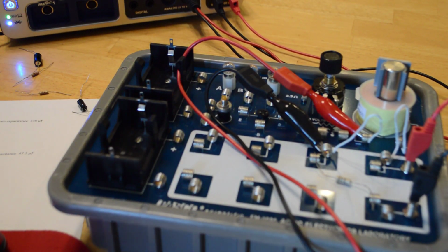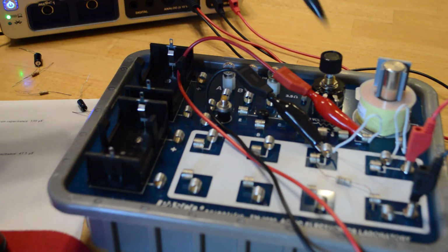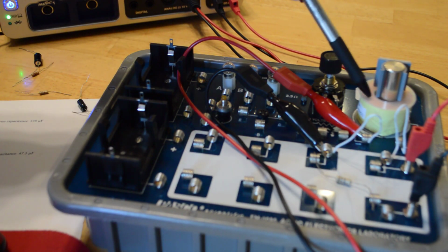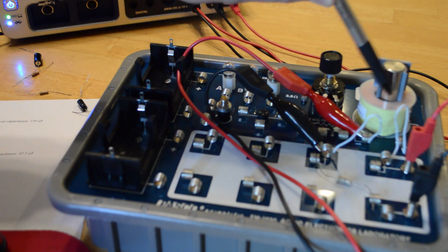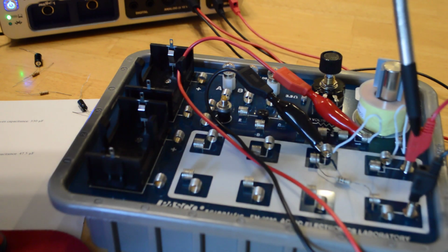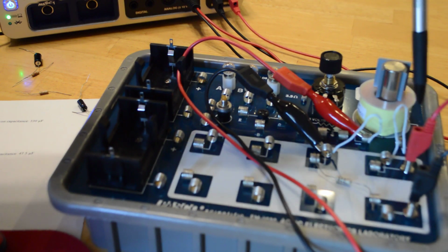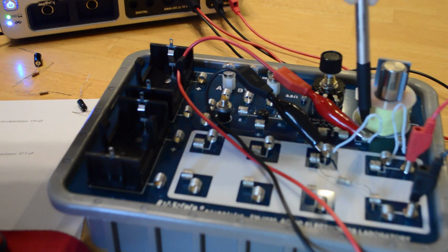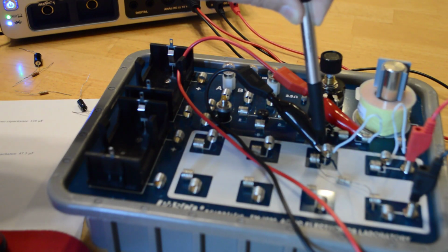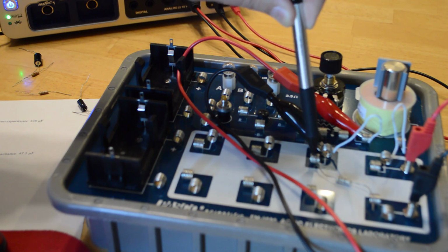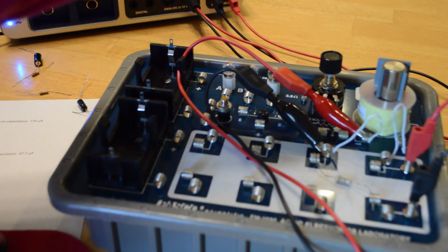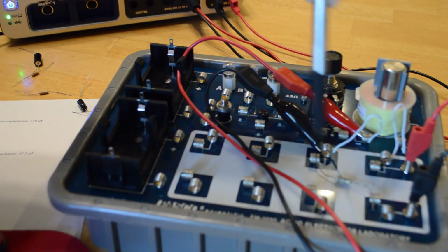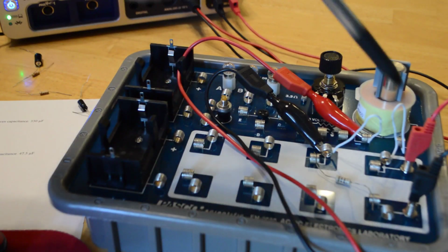Okay, here's the electronics kit now arranged with the inductance. Our coil is this device right here, and I put in an iron core to increase the inductance. Here's our input. I have a wire connection to the coil, and then another wire connection from the coil to here, and then I have my 10 ohm resistor from here to here, which goes back to the supply. So there's my simple series circuit, and then we're going to input a voltage.